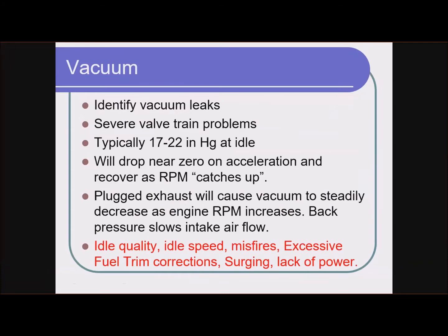So we know that if our vacuum is just low, right? It's supposed to be 17 to 22 at idle. If it's just low, most likely you have some sort of vacuum leak, right? So you're losing that vacuum somewhere else.